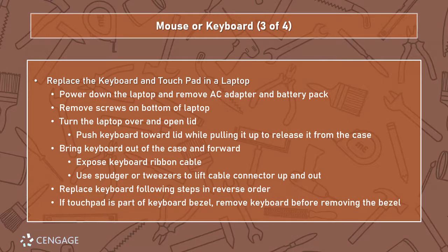If we're dealing with a laptop, we're going to go through the same steps we would for replacing anything in a laptop. We're going to remove the power, remove the battery pack, and we're going to read the service manual to see where the removal process takes us. So the service manual, of course, being a much better usage of our time to examine the teardown process than dealing with the user manual.